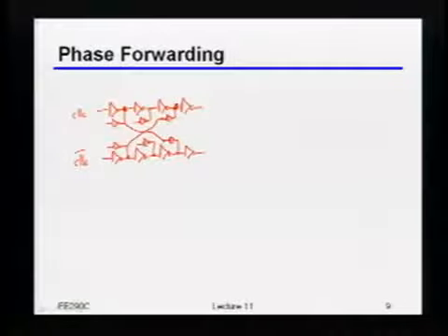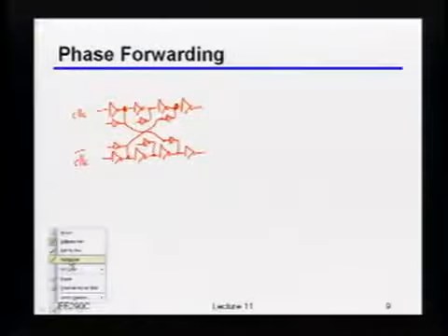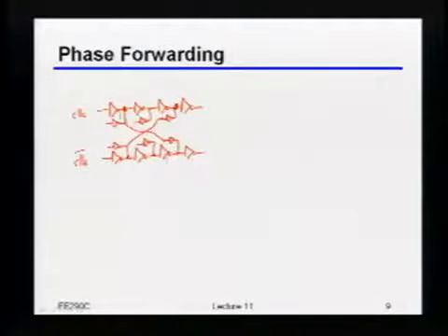And by the way, you'll do this in every stage. The idea here now is that I'm still going to guarantee that things are inverted from each other, because by adding those extra little inverters, I've made it really hard to start up in a bad position. But now notice, this thing starts transitioning before this one even does. To be more precise, this starts transitioning before this inverter actually gets its input signal. But it is moving in the right direction, because you know that if this starts going high, this is at some point going to have to go low.